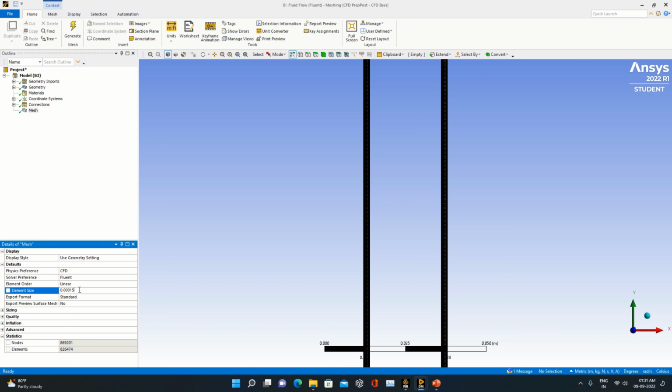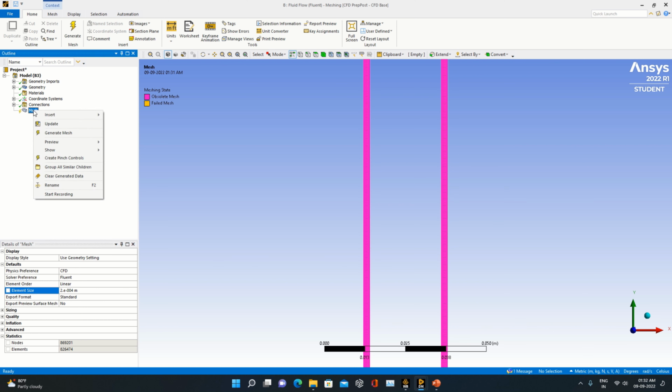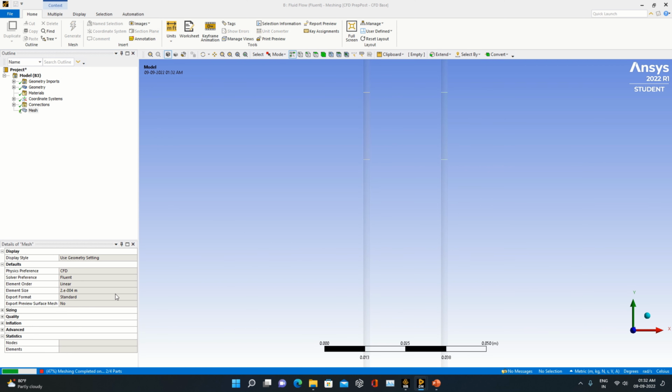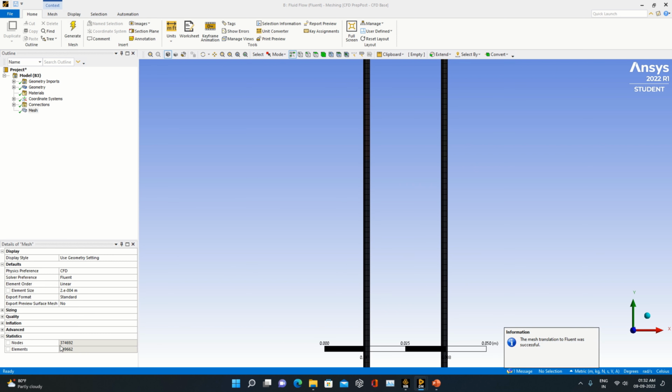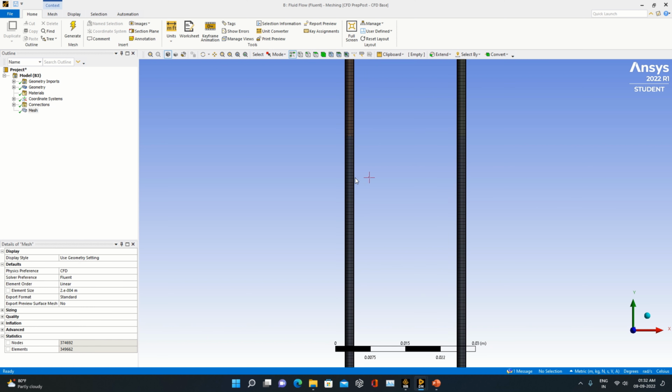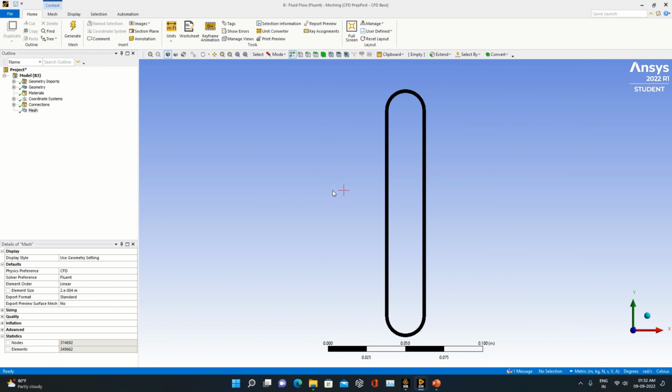So whatever we had taken earlier, like 0.0002, that was okay. Somebody can go with other values, like 0.15 or 1789, and just check out the number of nodes and elements you are getting. Right now I will proceed with the mesh size which is available here, with the nodes at 3,74,692. You can check the mesh in each of the cases.